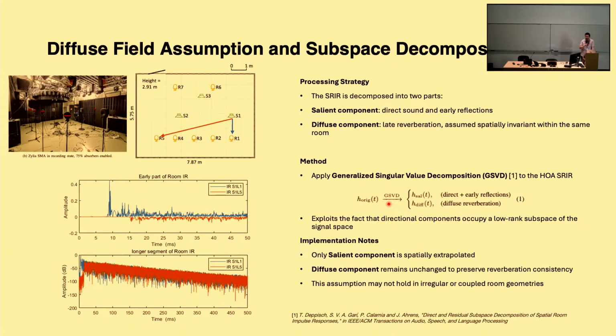Also adding to the last two comments, the advantage of the stereo microphone would be that it goes up to high frequency. The Zylia is, I think, limited to 3 or 4 kilohertz because of the spatial aliasing of the microphone array. It's a bit tricky, because they claim it's third order, but it's not for the full spectrum. It's just third order starting from a certain frequency up to 3 or 4K. This coincident setup would actually maybe be a bit better because it works in a larger frequency range, from low frequencies to high.